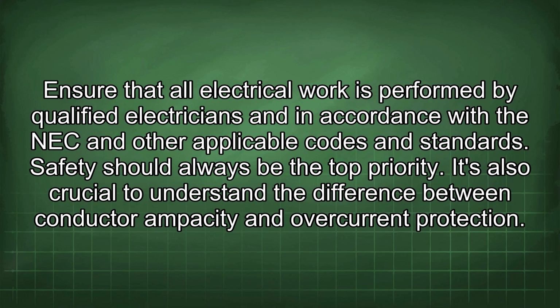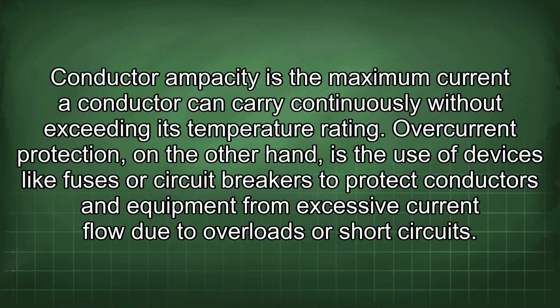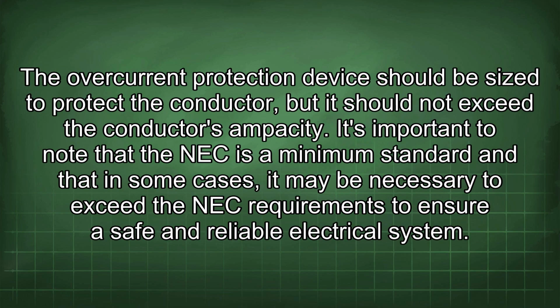It's also crucial to understand the difference between conductor ampacity and overcurrent protection. Conductor ampacity is the maximum current a conductor can carry continuously without exceeding its temperature rating. Overcurrent protection, on the other hand, is the use of devices like fuses or circuit breakers to protect conductors and equipment from excessive current flow due to overloads or short circuits. The overcurrent protection device should be sized to protect the conductor, but it should not exceed the conductor's ampacity.